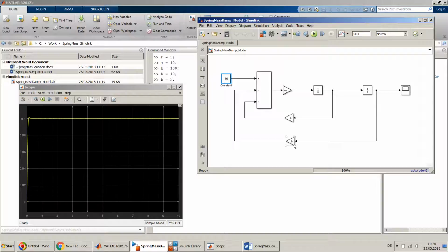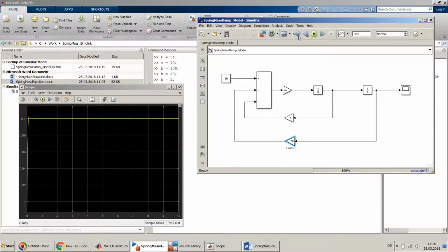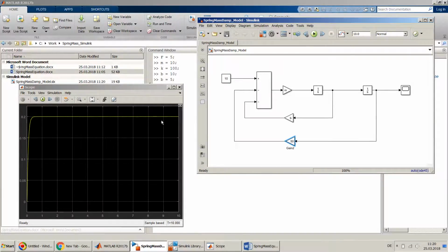Probably we can reduce our spring coefficient, from k to 50 and see how it happens. And we reduce our B and mass. So somehow I'm trying to bring it to an underdamped system. I want to see waves forming here, which I am not able to see.